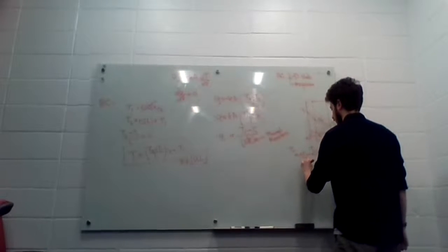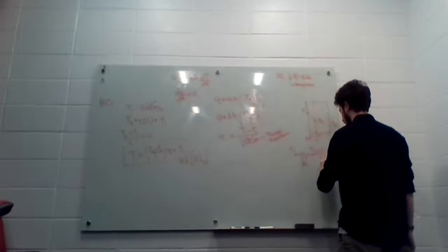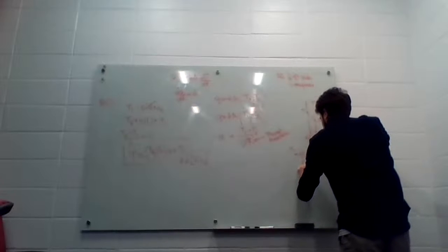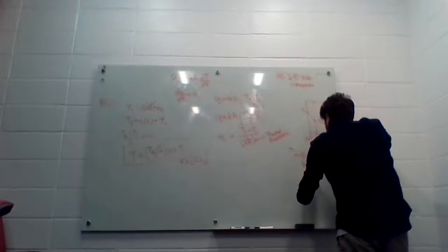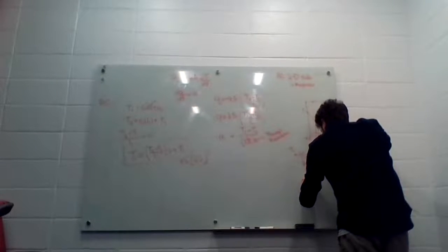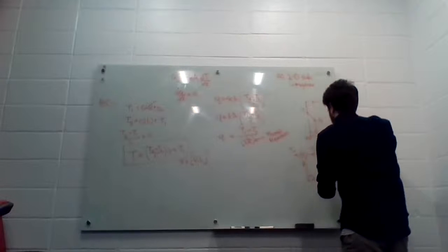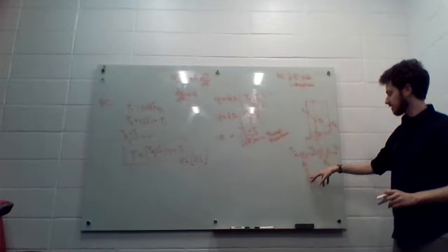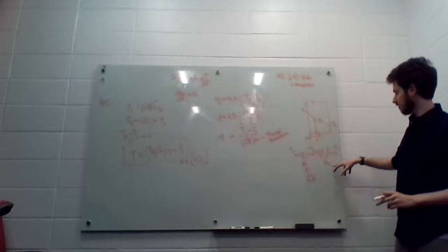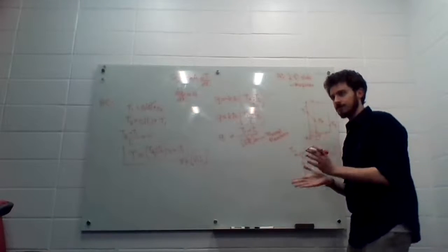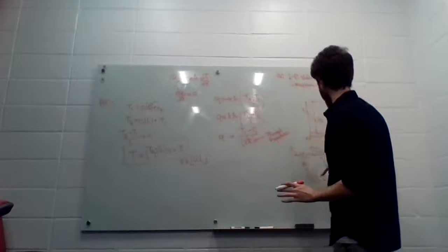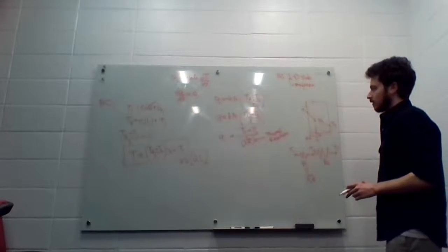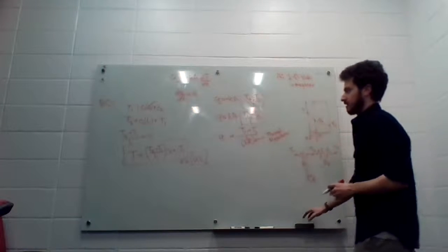So we're just going to label this R1, and this is R2, resistance 1, resistance 2. Resistance 1, we're not going to really use this right now, but it's L1 over K1 A. A is the same for both. That's really important. This is some length and some thermal conductivity. R2 is some other length, some other thermal conductivity. For brevity, we're just going to keep them as R1 and R2. I'm going to move back to the side of the board. Everybody have this?